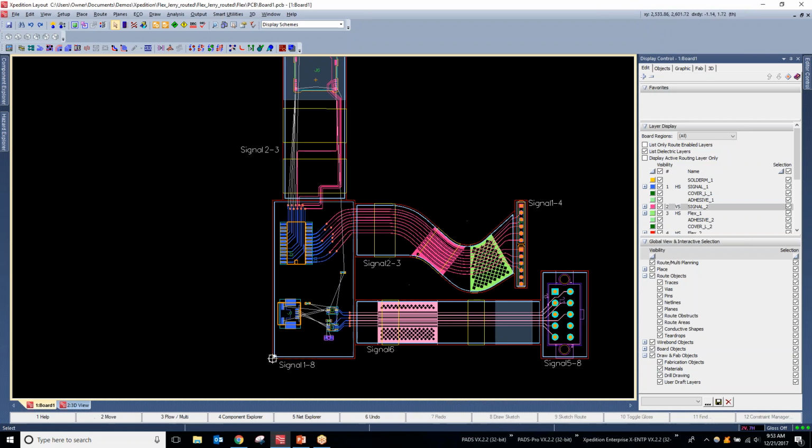All right, so we've got our multiple board outlines defined. You'll see here we have 1, 2, 3, 4, 5, 6 different board outlines defined, and that allows us to define 6 different stackups from that master stackup. So it's really easy to start your design and set up the stackup correctly first. That's really powerful and important, to start off with a correct stackup at the beginning of your design in order to make sure we're off on the right foot.